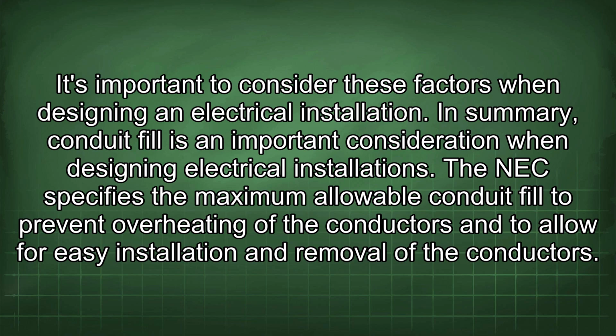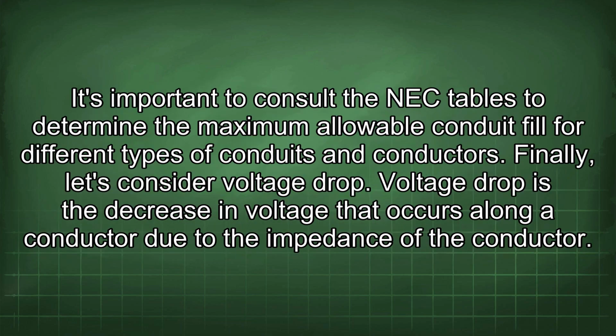In summary, conduit fill is an important consideration when designing electrical installations. The NEC specifies the maximum allowable conduit fill to prevent overheating of the conductors and to allow for easy installation and removal of the conductors. It's important to consult the NEC tables to determine the maximum allowable conduit fill for different types of conduits and conductors. Finally, let's consider voltage drop.